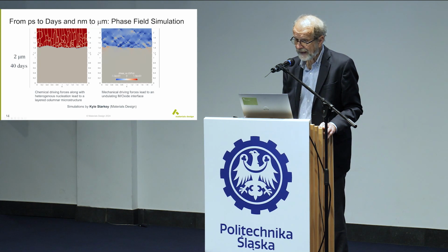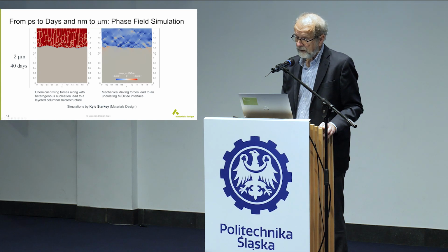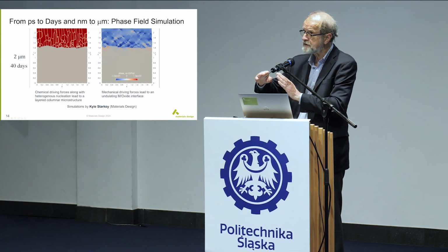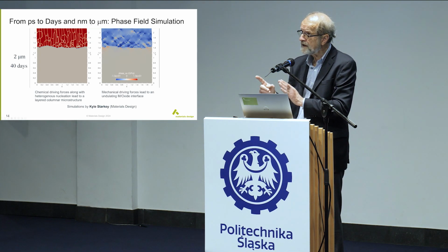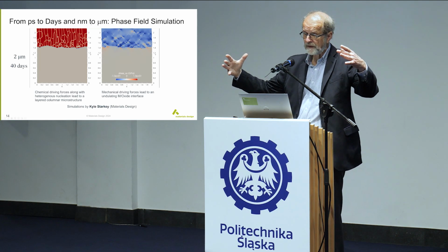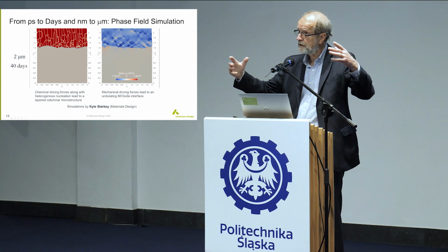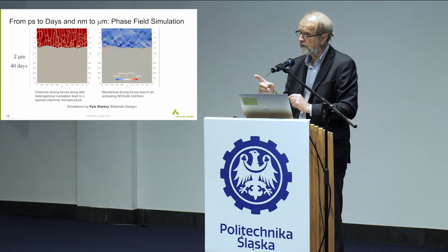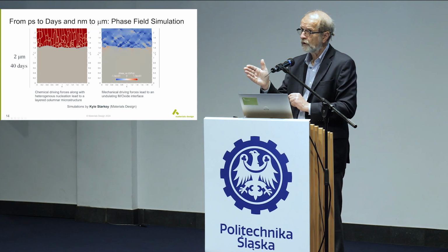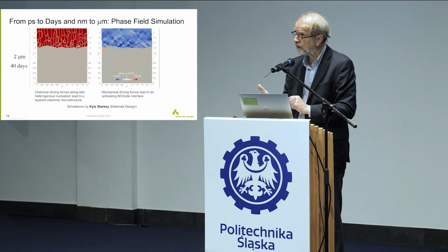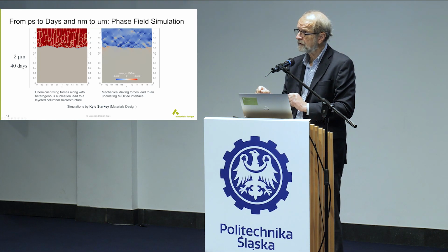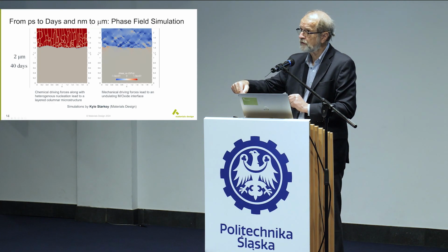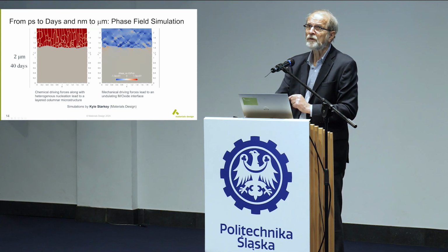And this is the analysis of the stress. Because you have a curvature, an interface that is not flat, you get regions where, despite the fact that the entire system is under compressive stress, there are local regions that are under tensile stress. If you have tensile stress, you can form cracks or nano slits and nanopores, and they have been seen in TEM experiments. And if you have nanopores, those are pathways, highways, so to speak, for hydrogen to get in.